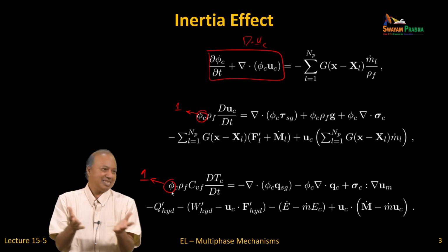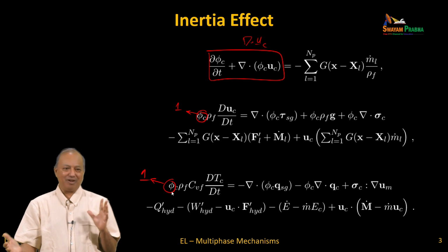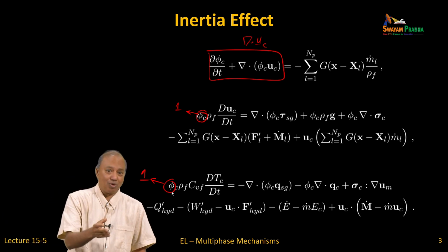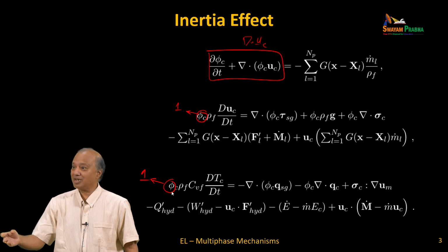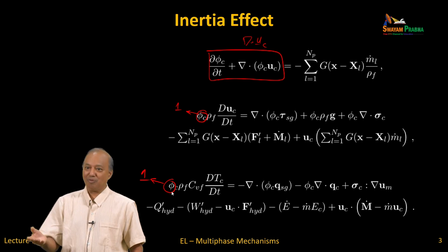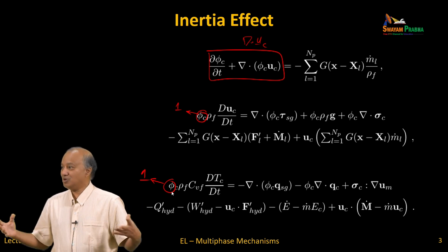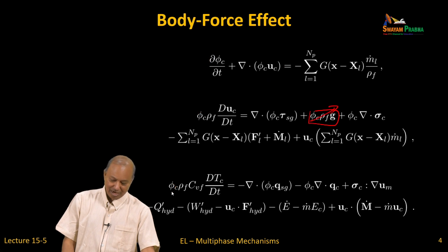So, it's basically both inertia effect and volume effect if you don't care about them. So, if your mass loading and volume fraction are small, if volume fraction is small, volume effect is negligible. If mass loading is small, in other words, the two-way coupling is not due to the fact that you have a lot of particles, then this significantly changes.